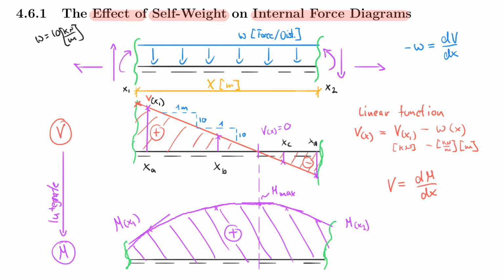And so we related each of these shear force values to the slope of the moment function, because we know this here, and therefore we can unmistakably draw the parabolic function and the shape of this moment diagram. And let's talk about the unmistakably part here for a second. So students sometimes tend to think, this is positive here, therefore my moment diagram must be positive. But you can already tell from this diagram that this is not the right logic, because here it's negative and my moment diagram is not negative here.